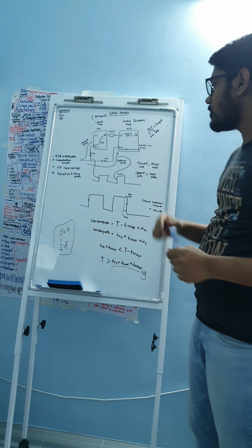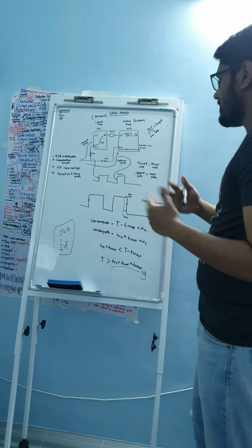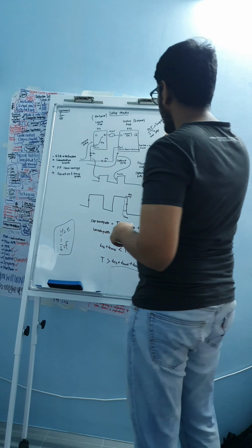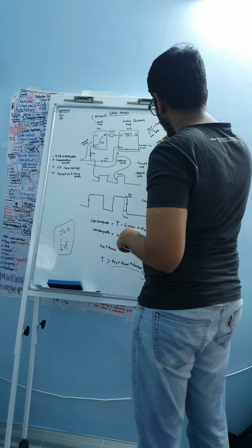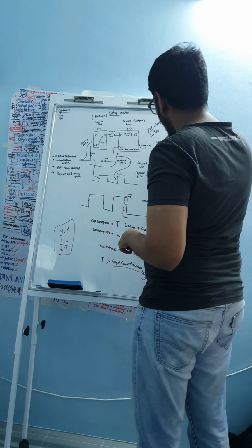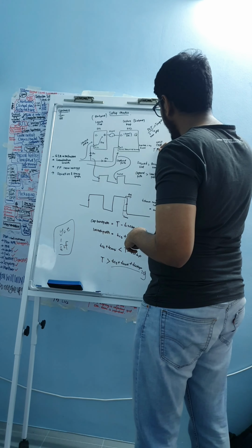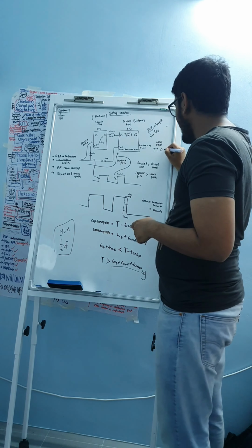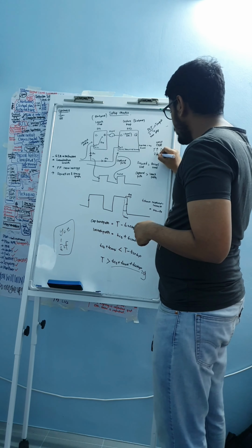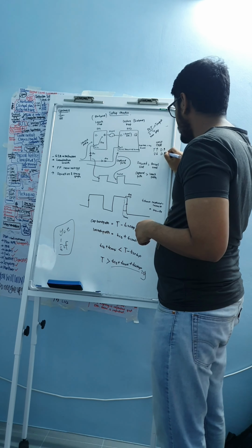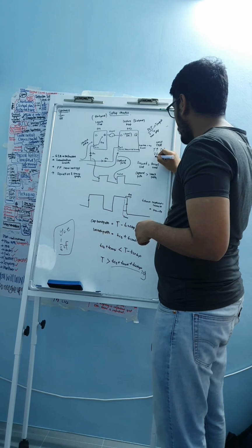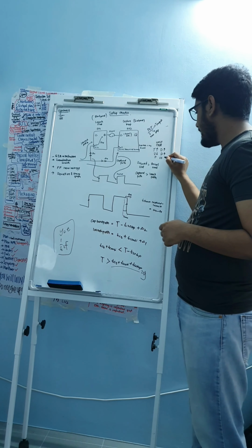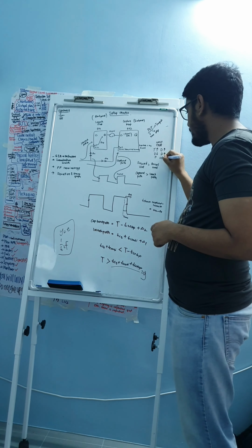and also results. So over here, as we know, if you want to make it a worst case for setup checks, worst case for setup check. When T, the temperature, is higher, your delay is going to be higher. Whenever your voltage is lower, your delay is going to be higher. Whenever your process is slow, then your delay is going to be higher.